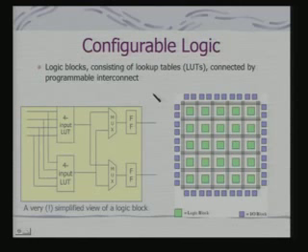We are seeing that we have got a set of combinational circuit blocks, we have got a set of flip flops or registers, and if I have these set of blocks and if I have the freedom to connect them in any way I would like, I can synthesize any combinational or sequential logic functions. And any hardware unit which is doing any kind of function, therefore, can be synthesized through these kinds of FPGA blocks.